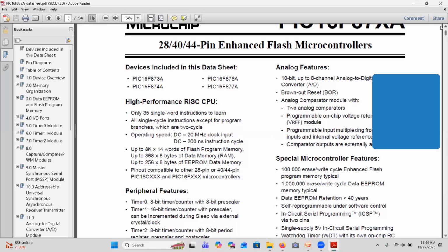When the multiplexing value is changed to 1, they will take it from the next channel. In that time, other channels are in high impedance state. Though there is a signal input, they won't consider it. So like that, they use multiplexing to digitize one input at a time. They can use a timer to choose different multiplexing values. They won't digitize all of them in one go. They will use time division multiplexing, so based on different timing, they will come and digitize the samples.